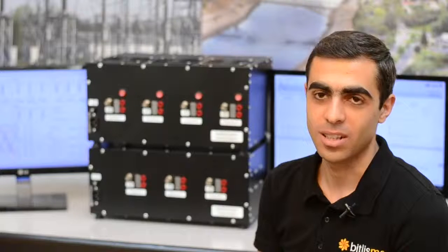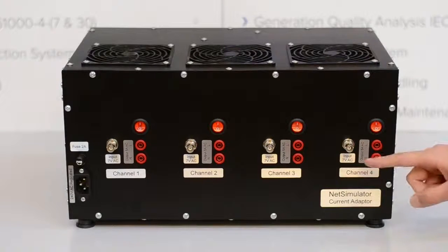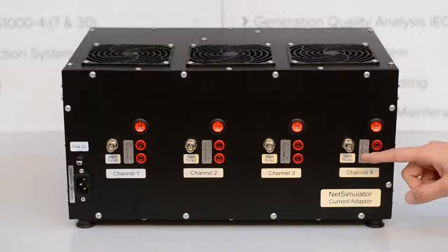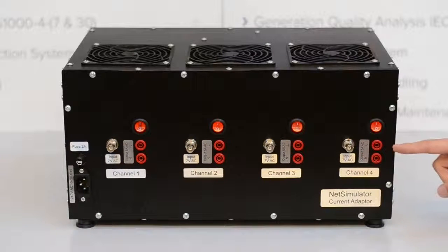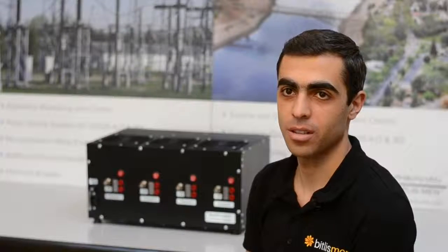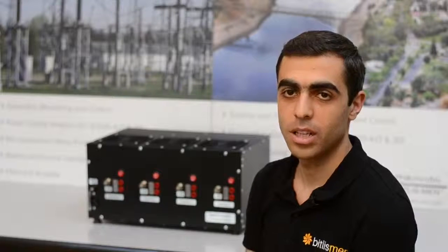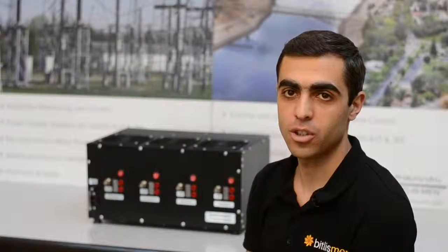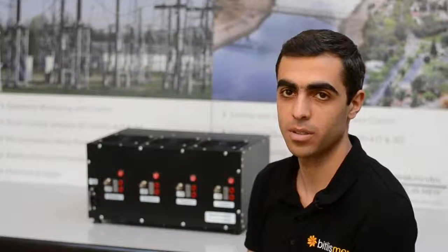Now let's look at the current adapter. Here as well, the input signal ranges within 7 volt AC or DC signal, and the output ranges up to 5 ampere AC or DC. This adapter converts the input low voltage to high current signal, acting like a current source. It will replicate the low voltage signal shape and spectral band up to 64th harmonics within 0.5% error. For detailed specifications, please refer to datasheets.